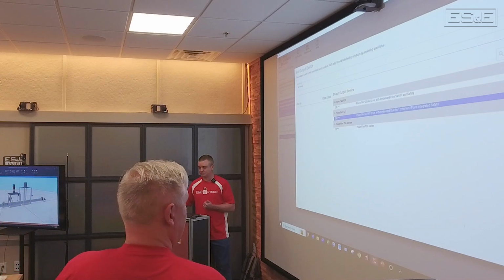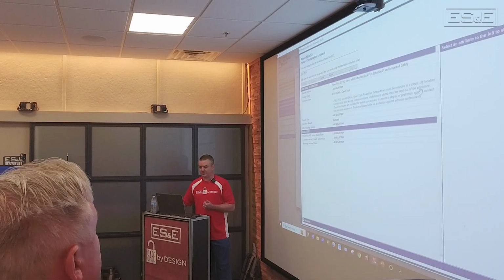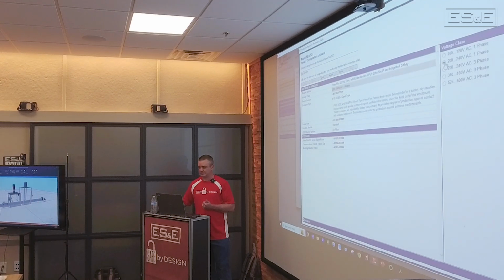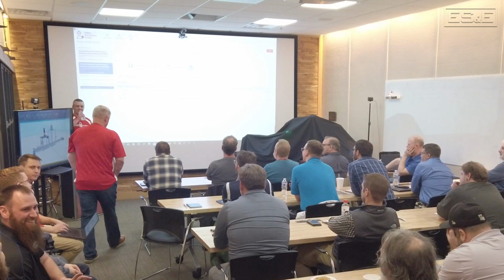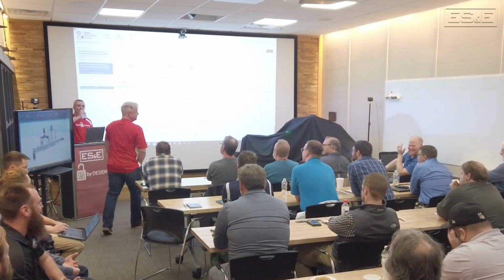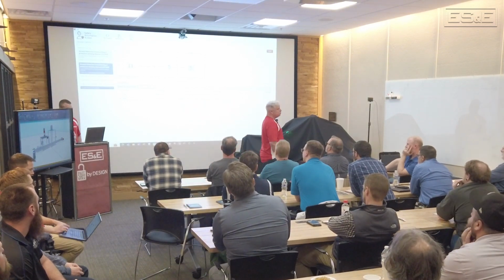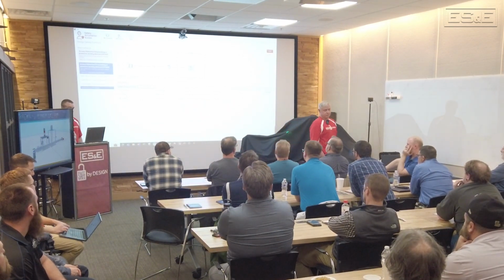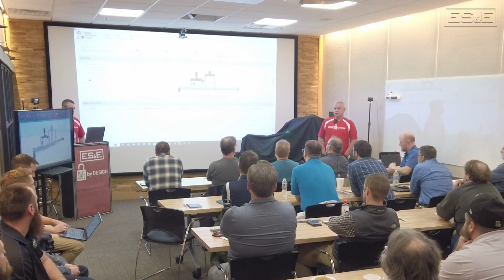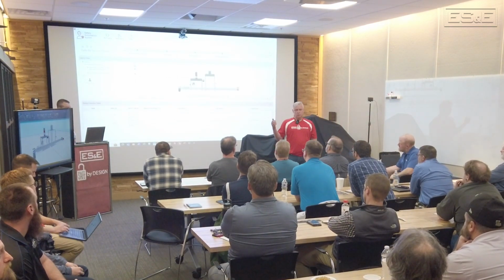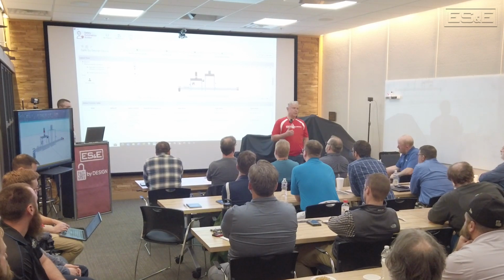All right, cool. So again, we'll have to do the configuration of it. The 527 is our motion drive. It's still a PowerFlex drive. It's not a Kinetix drive, but you control that drive with motion instructions, right? In fact, you have to have a motion capable controller in order to control the 527.